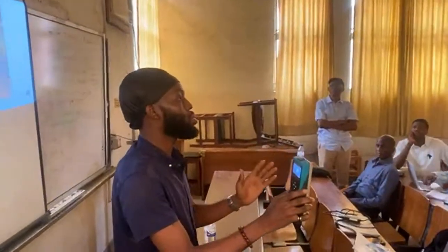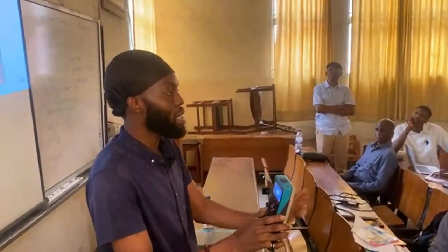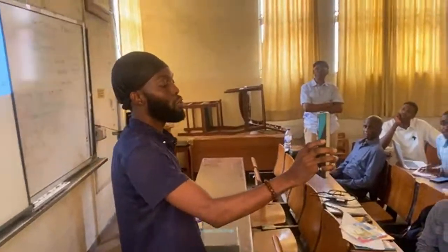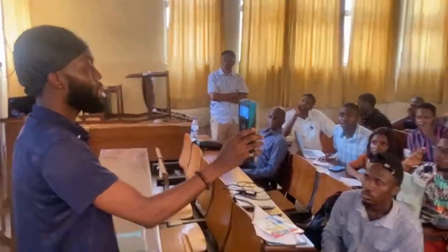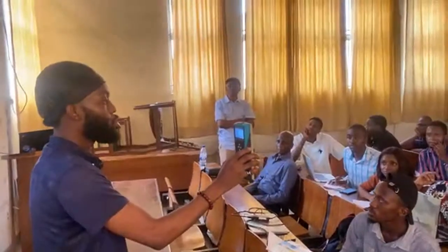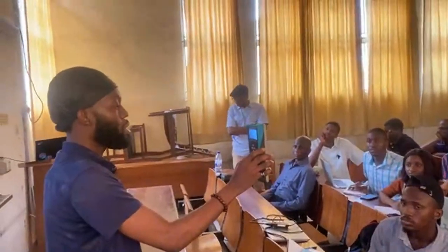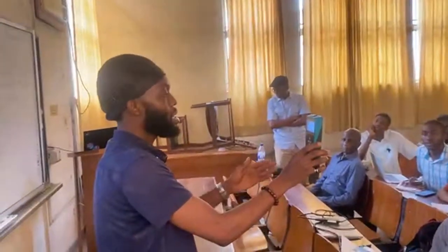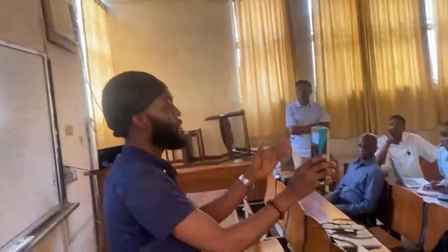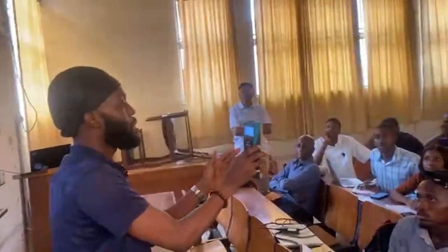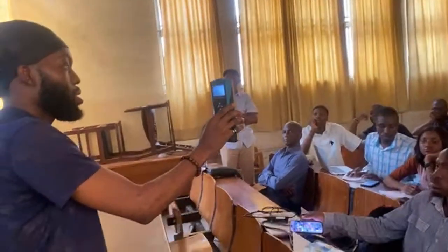When you put your rebar detector on it, trying to locate the rebar, it shows one rebar here, then in the next 25, 30 mm it shows you another rebar. Then you know that's an error. You refresh it. Or it's not even showing you any rebar. Then you refresh it and put it back on the structural element to check whatever is going on.